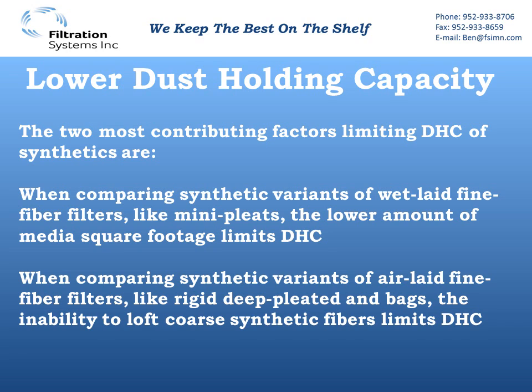Save a lot of places and a lot of strands of media for the filter to catch, and then allow air around those particles and around those other fibers. So you have very, very high dust holding capacities compared to the square footage of media. We just can't get that lofting currently out of the coarse synthetic fibers. So again, that will limit its dust holding capacity.